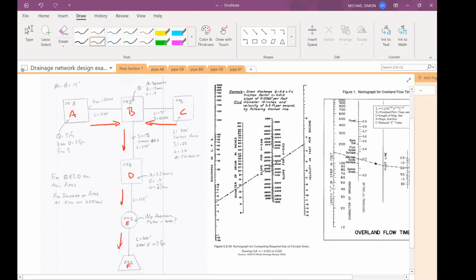Now, along the way, I gave you some constraints. The only reason I gave you constraints is that I want us to have some ideas of why we choose certain pipes for certain reasons. There will be cases where we want to keep the slope at a certain pitch because we want to make sure the pipe doesn't stick out of the ground. It's got to stay underneath whatever the road surface may be. There'll be times where we want to keep the velocity of the water either higher or lower depending on what's coming in. Again, we always want to keep that water speed between 2 and 8 feet per second. Those are our realistic numbers to keep it between.